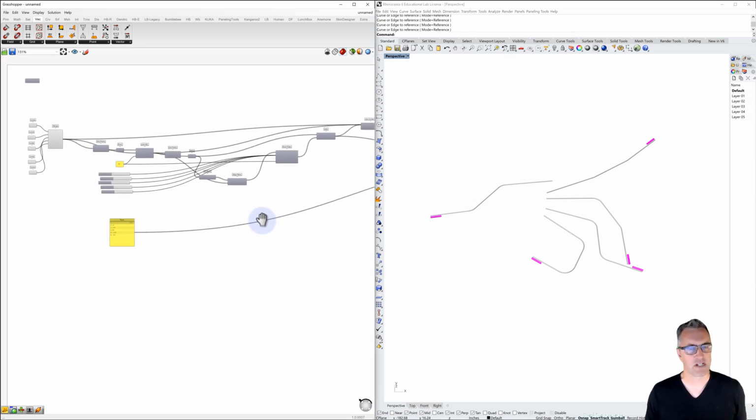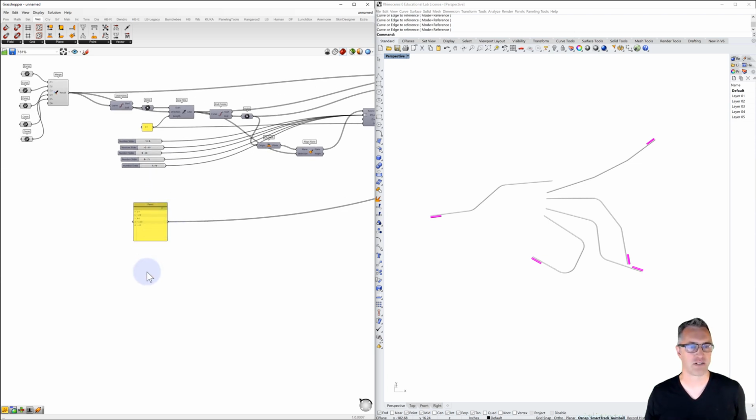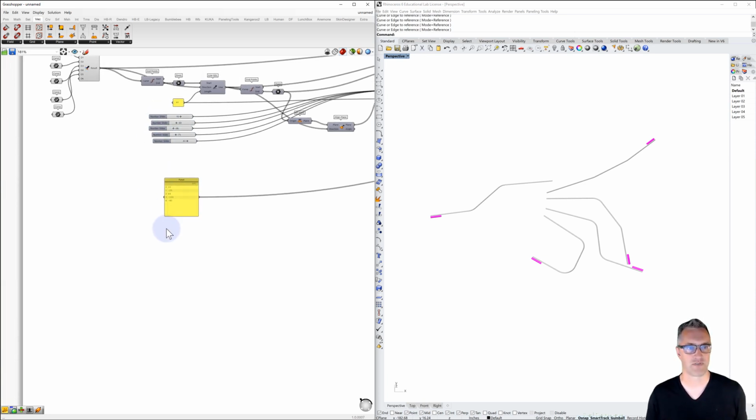As I've done, because I like using Grasshopper as a design tool to explore options, I am a fan of random numbers. What's nice about the random numbers is that we can control its min and its max, and we can set those, and the random numbers are a nice way to iterate on a lot of different options in a kind of finite way, using a specific parameter. So let's make 5 random numbers for this first range over here.